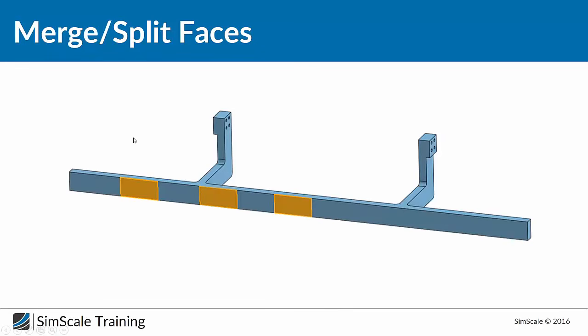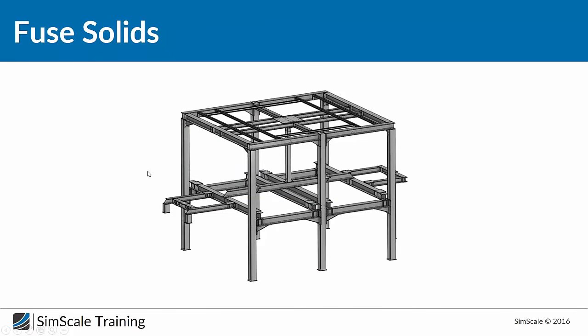And therefore, really the first step, as I mentioned, is to prepare the CAD model and really think about what you want to do. In the best case, you should have the whole simulation set up before your eyes and then start to prepare the CAD model. And the last thing you should consider is related to simplifying.